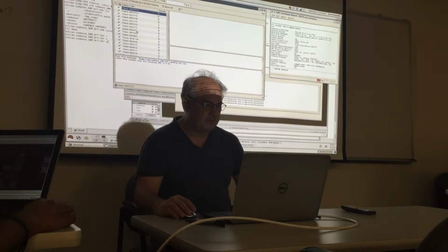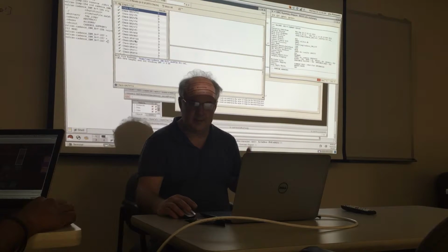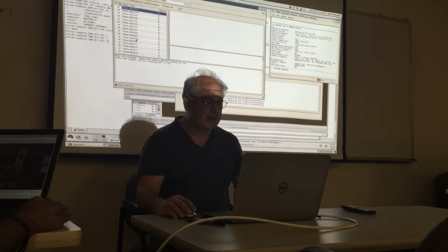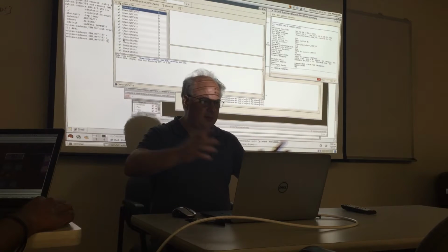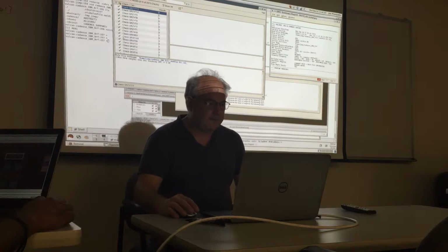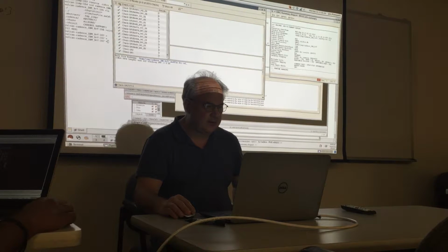And the results by default are going to show all the rules that were applied and checked. And a lot of these actually aren't even relevant to the cell that you're checking. But it'll give you a green check if either it wasn't applicable or it passed. And so it's quite a list. There's 2,070 checks that it makes. And it does it very fast, okay? And all these are the design rules associated with this technology.